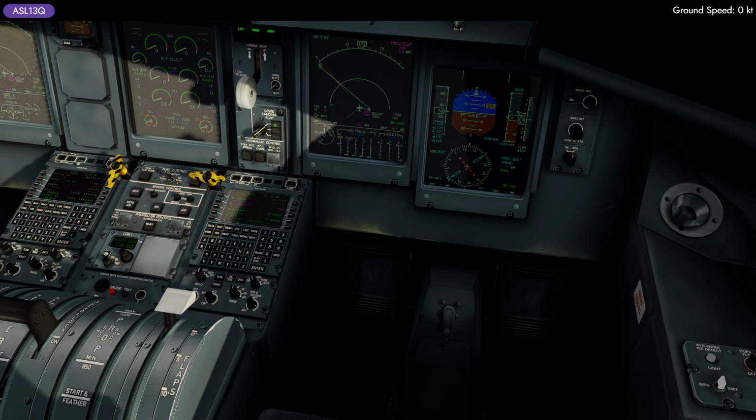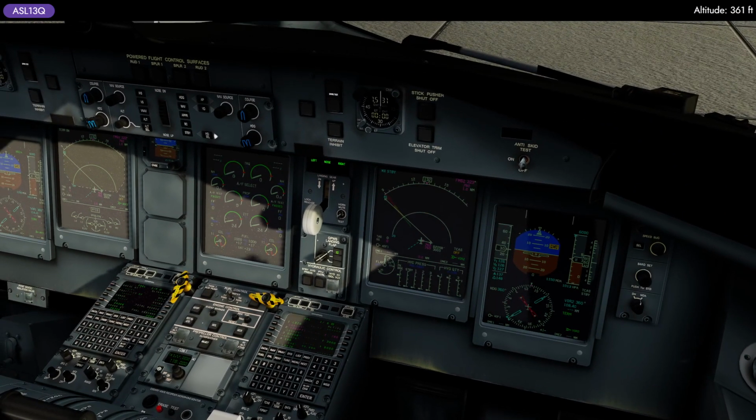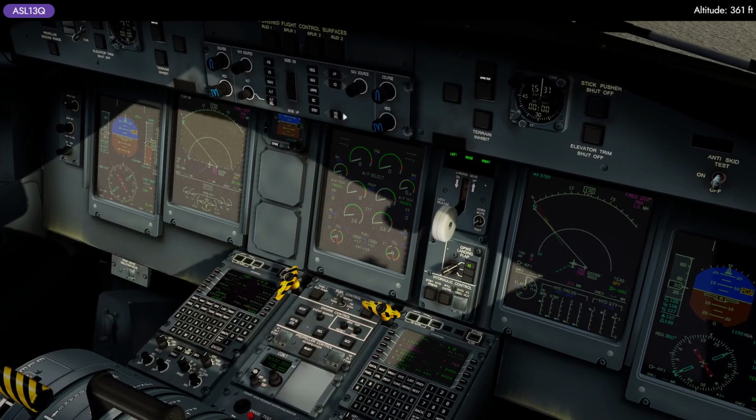So basically at this moment, when we pass this altitude, we are going to reduce to the climb, that is the rating of 900, continue until we reach 3300, and then we are going to actually retract the flaps and increase our speed. Since we are going to climb V2 plus 2, our V2 speed is 127. So we can now proceed with this configuration.